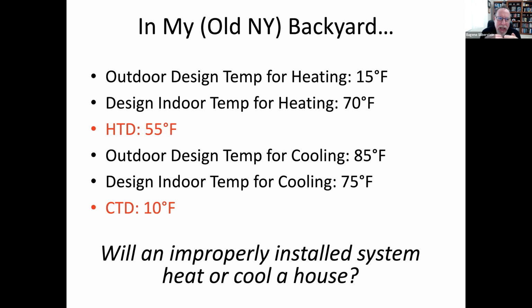Now, when we get into the cooler winter months, now we're asking that same system that wasn't properly sized, installed, charged, with improper airflow, we're asking that system to push against 55 degrees. So any imperfections in system design, charging, airflow are going to become more obvious.